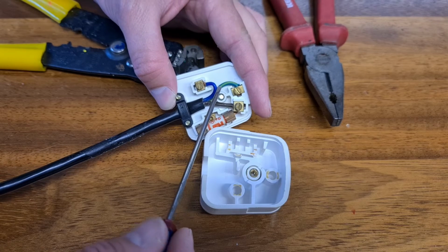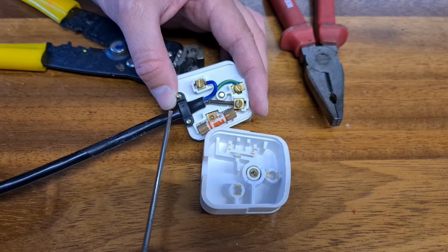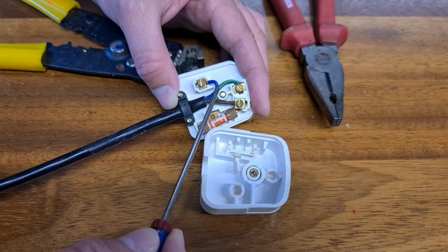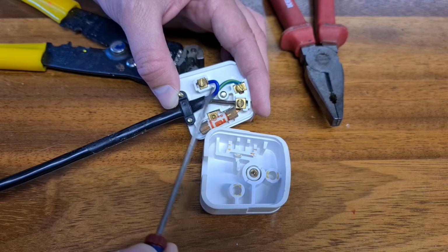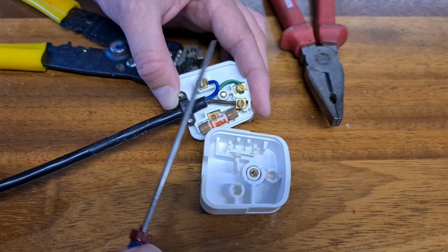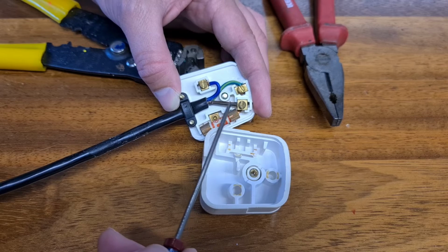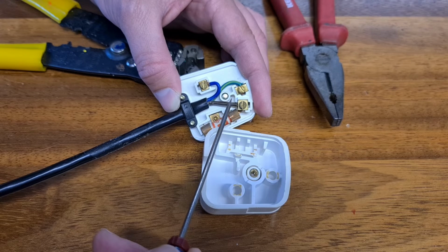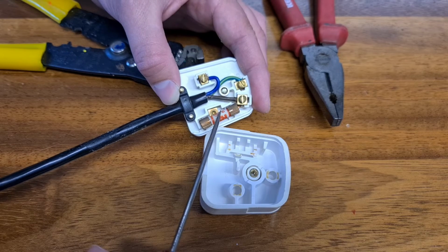A green and yellow striped wire is an earth wire to protect the circuit if something goes wrong. Here, the neutral wire should normally stay at 0 volts, with the brown live wire oscillating between positive, well, it can be even more than 230 volts, but on average about 230 volts, positive and then negative, then positive and then negative. This is the wire that needs to be cut off in the event of an emergency. And so that is why the fuse is connected to that.